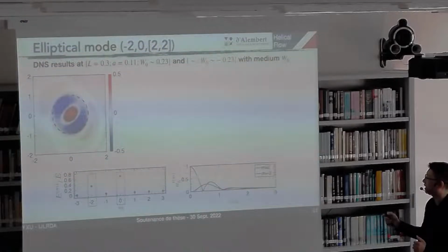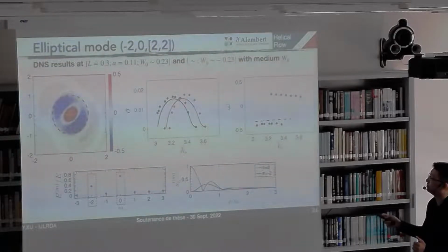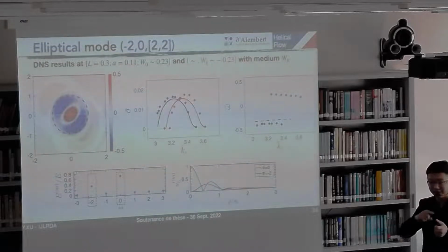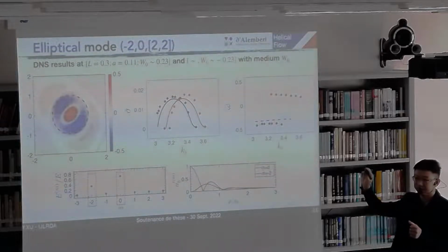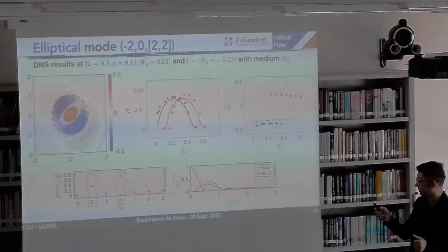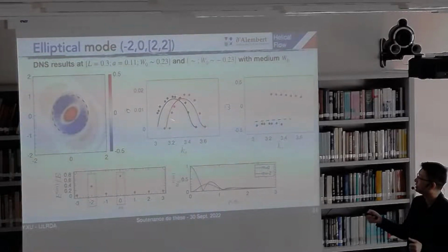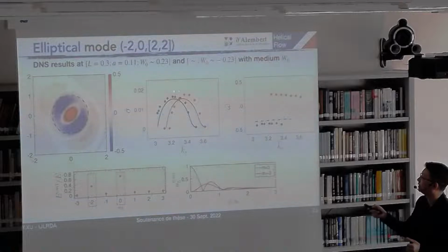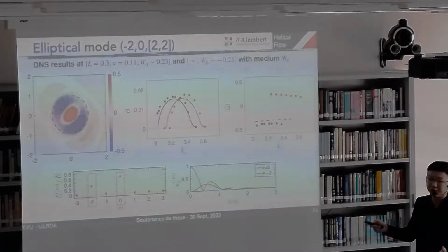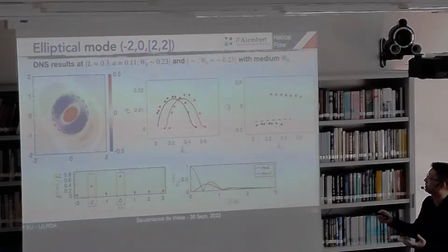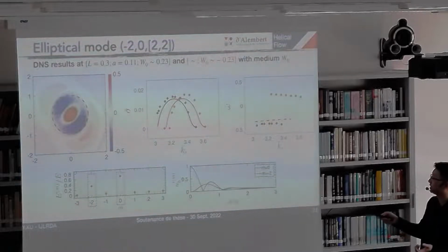On the other hand, we just did another simulation with reversed axial velocity. For helical motion, if it's positive, it means it's going in this direction, but if it's negative, it's going in the opposite direction. You can find two theories corresponding to the different directions here, also by Blanco with some corrections we have added, and those are our simulation results. We can find that in both cases the unstable range fits quite well with the theory, and also the growth rate, but it still has very little differences. And also for the frequency, we obtain a quite good value.